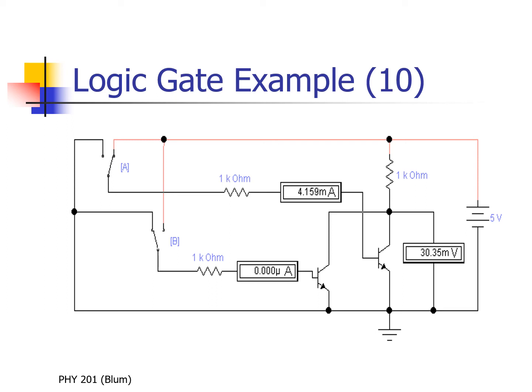But these two now effective resistors, one high resistance and one low resistance, are effectively in parallel, and so the overall effect is a low resistance, just as it was for the previous state. So in the path of the battery from the 5 volts through the 1 kilo ohm resistor at the top, and then down to these parallel transistors that have the effect of a low resistance, most of the voltage is dropped still across the 1 kilo ohm resistor, and there's only a little bit of voltage left to go through the transistors, and so that voltage is low. So we put in A is high, B is low, and our output for the circuit is low.